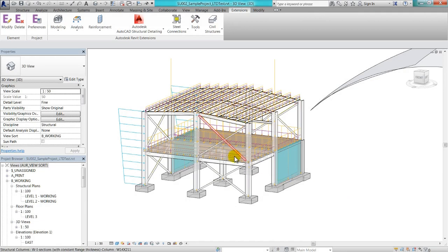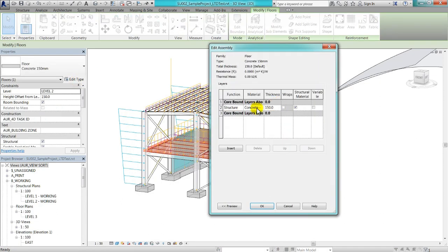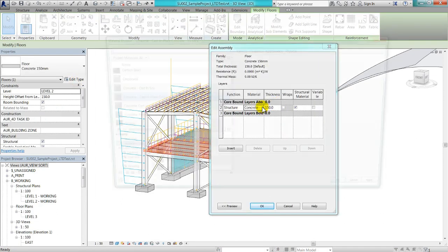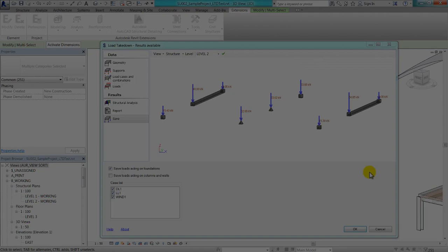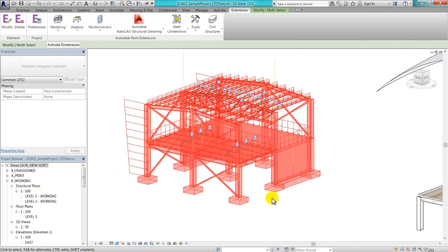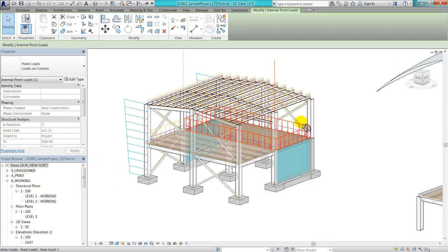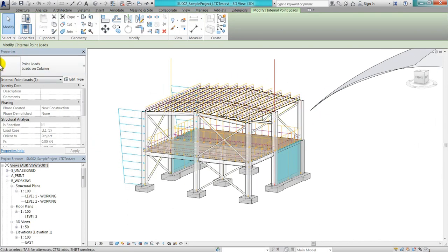The load takedown tool uses the material property for the density or unit weight from the model. Ensure that the material definitions are properly assigned for the elements selected for load takedown. Resulting point loads and forces on supports can be written back into the model as reaction forces. Unfortunately, the other analysis tools, for example the Gravity Column Designer, can't use this information.